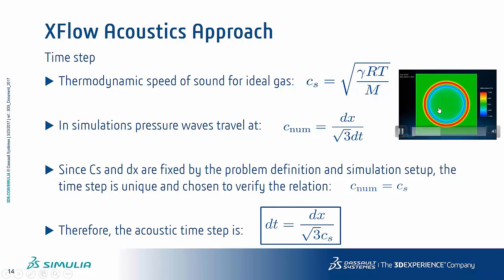And so you see, for example, this is what you get here: if you've got a small perturbation in the center of your empty domain, for example, initially we just throw a pulse, and then this pulse will just propagate, as you can see in this simulation here. So this propagation will be handled by the streaming of the PDFs, and this will be relaxed with a collision operator to the equilibrium state. So we already see all the fluctuations of the fluid due to the compressibility of the fluid in Lattice-Boltzmann, which is why it's also very good.